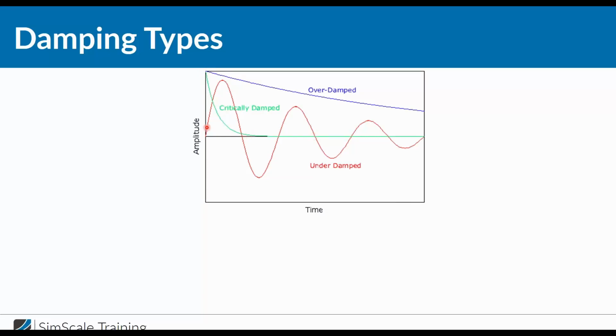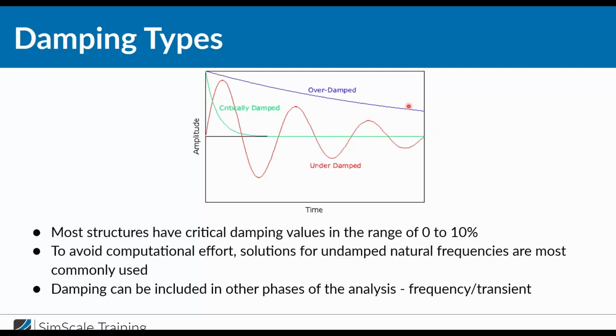If it's overdamped, it goes down slower, but it takes longer overall. We hit the intersection with the x-axis a little bit sooner than with critical damping, but then it goes in the wrong direction and back. Underdamped means that there are a lot of oscillations, but fast, and overdamped means it's quite slow, but without any oscillations.